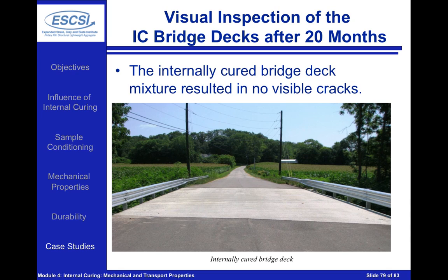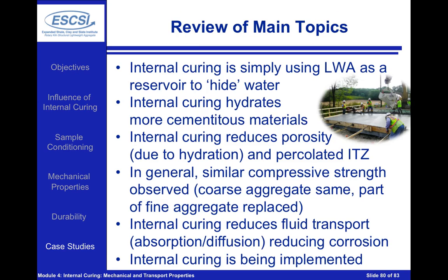Now, I want to be very careful that even though this particular bridge deck showed no cracking when it was internally cured, we need to remember that cracks can occur for other reasons other than just shrinkage. So we need to be very careful to understand that while internal curing can help to dramatically reduce our shrinkage cracking, it may not prevent all the cracks that can form in the system.